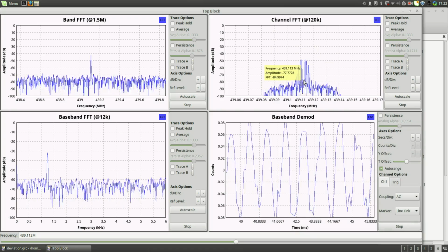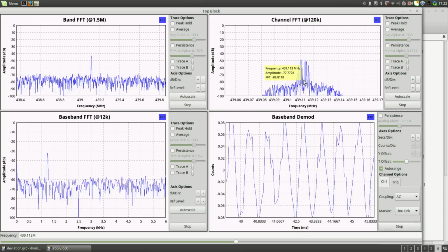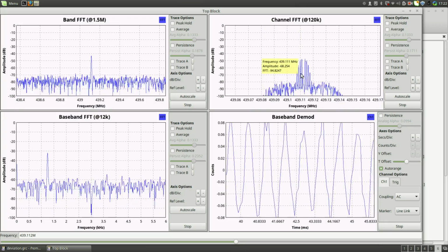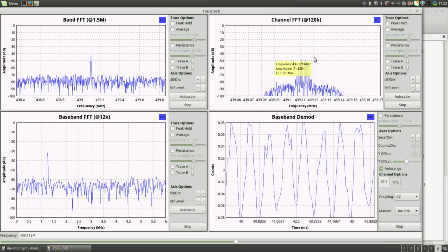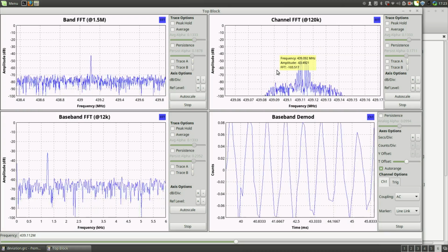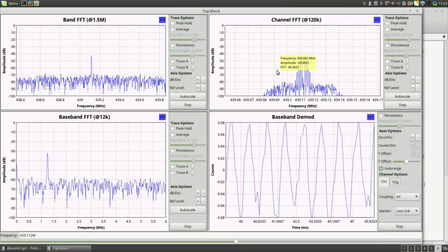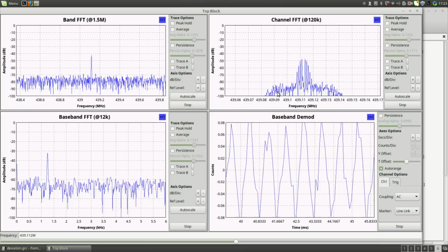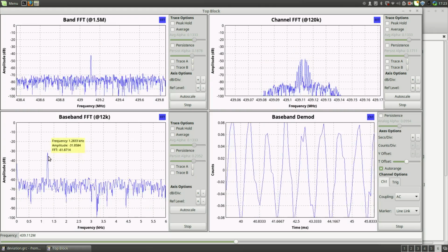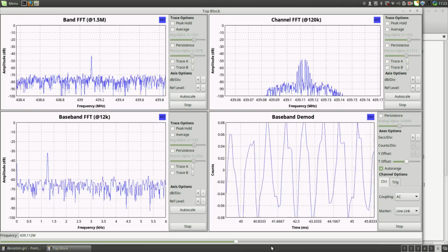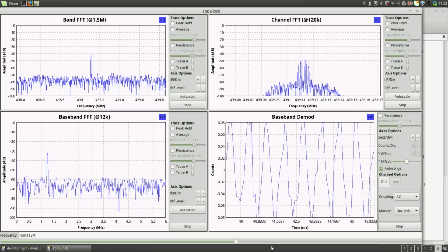I'm wondering whether it is a coincidence that it's just 2.42 volts peak to peak, because that's sort of an interesting number. But anyway, so there is that. So we have, for a frequency waveform, a sine wave of 1.245 kilohertz, at this particular amplitude we managed to get rid of the carrier, and the rest is just business as usual. I've got this peak here and also a sine waveform here. So let's grab some pen and paper and discuss whether we can use this for anything useful.